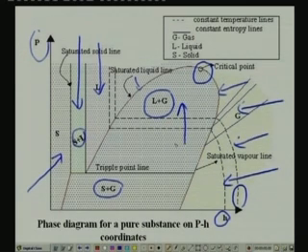This is very important, and we shall see later how this influences the selection of refrigerants. And physically, when the working fluid exists below the critical point, you can distinguish liquid and gas. That means if you have collected this liquid and gas mixture in, let us say, a glass beaker, then a meniscus forms between the liquid and gas phases. Whereas if the working fluid is above the critical point, you cannot make any distinction between liquid and gas, and that region is known as the supercritical region.